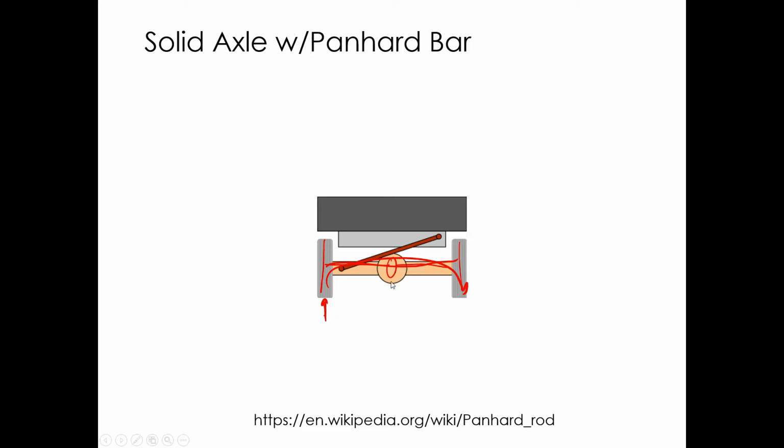Roll centers on this are tricky because it depends on how you mount the car to it. Often, like on trucks, these will be mounted with leaf springs, and there's not a really good roll center because the leaf springs are mushy, so the roll center kind of moves around all over the place and isn't in a defined spot. If it was controlled by a 4-bar linkage or something, you could guarantee the position of the instant center within the stiffness of the links. With leaf springs, the whole thing's compliant, so who knows where the roll center is going to end up being.